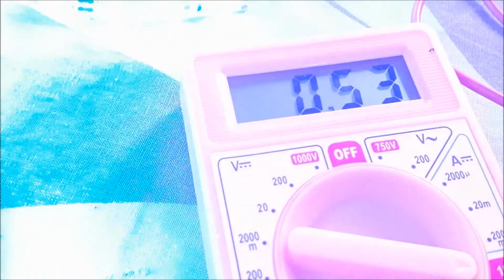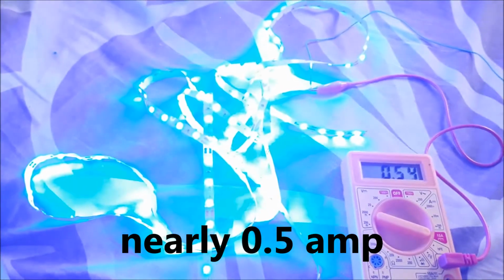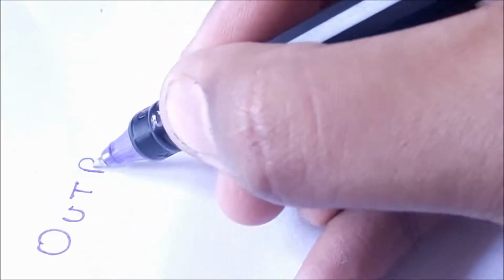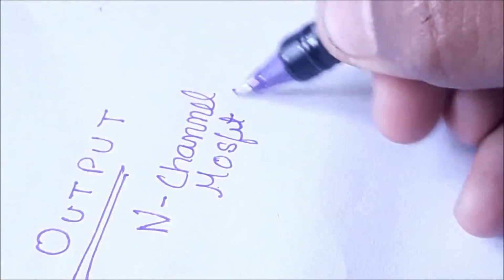At last, output. Now comes the last component that we need. As we want to control an LED strip, which consumes a higher amount of current than my microcontroller can handle, we could use a relay. But using a relay will not allow us to switch between different brightness levels, so we are not going to use it.